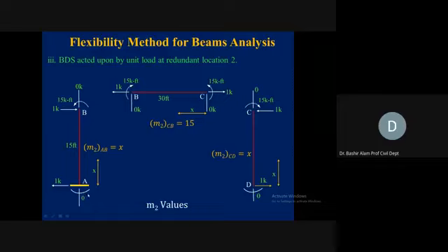Now, starting from A, we put AB in equilibrium. So 0 upward, so 0 here also at B in the Y direction. Summation of Fy is satisfied. 1 kip is leftward directed, so 1 kip in the rightward direction. So summation of Fx is satisfied. Now this 1 kip and 1 kip make a couple.